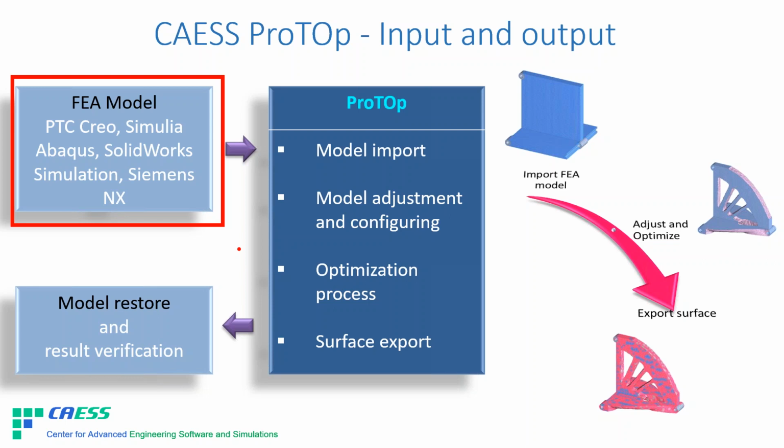And in topology optimization, when you finalize your result, the mesh really has to be fine, because it is actually the same as in digital photography. If you have a pixel of 1 by 1 millimeter and a picture size of 10 centimeters by 15 centimeters, you cannot get a nice picture. This is impossible. So you have to have really fine pixels, and in topology optimization, this translates to fine elements. There is no way around fine elements.